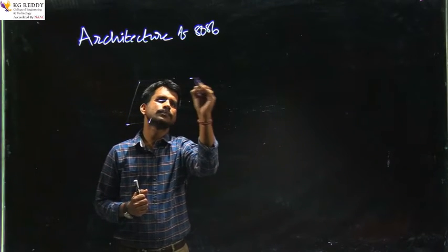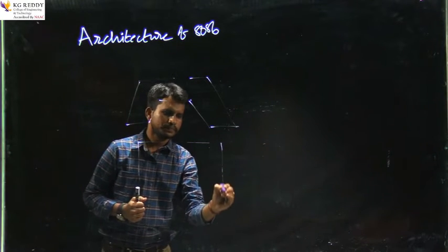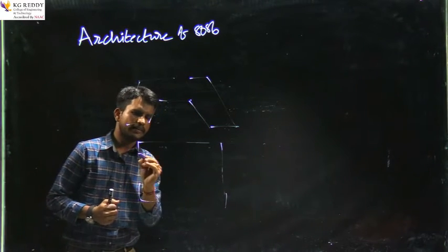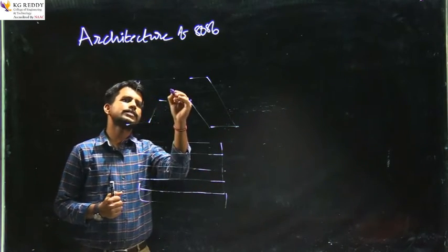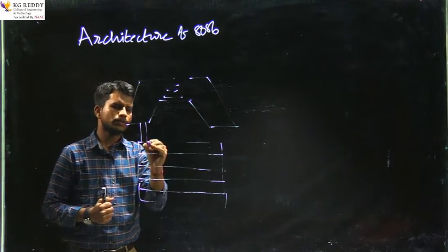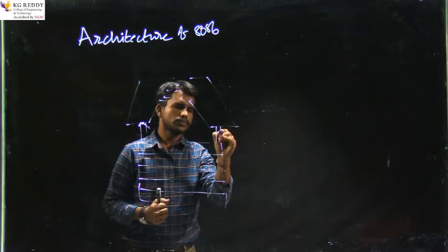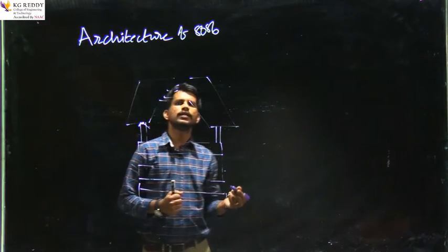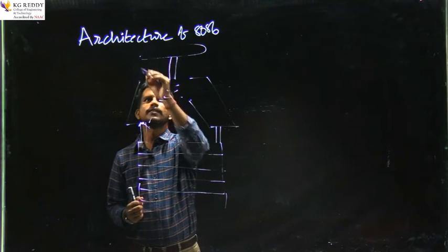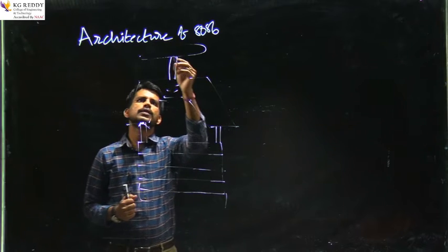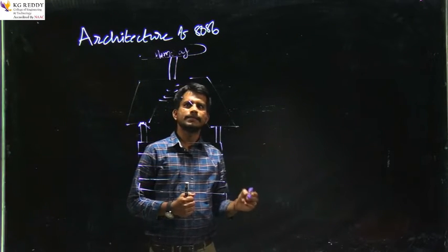an adder circuit and a set of registers. All the registers are of 16-bit size, and these set of registers are called segment registers. And this is an adder circuit which is used to perform the address addition operation. To show the physical address location of memory where exactly the data is available, we will use this adder circuit, where we can add the effective address and base address of the instruction, and it will locate the physical address location of the memory where the data is exactly available.